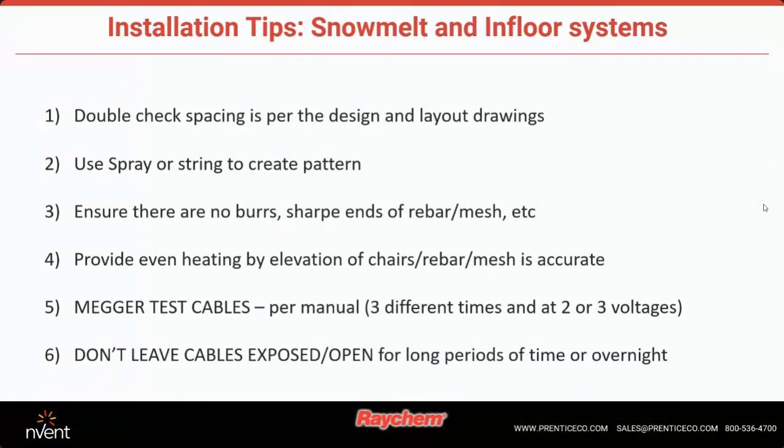And then lastly, I'd say this again, because this is probably the #1 thing that I find becomes a problem, is when water gets into the cable. If it has not been secured, even securing it with electrical tape at the ends is better than leaving it open to atmosphere and allowing water to get in.